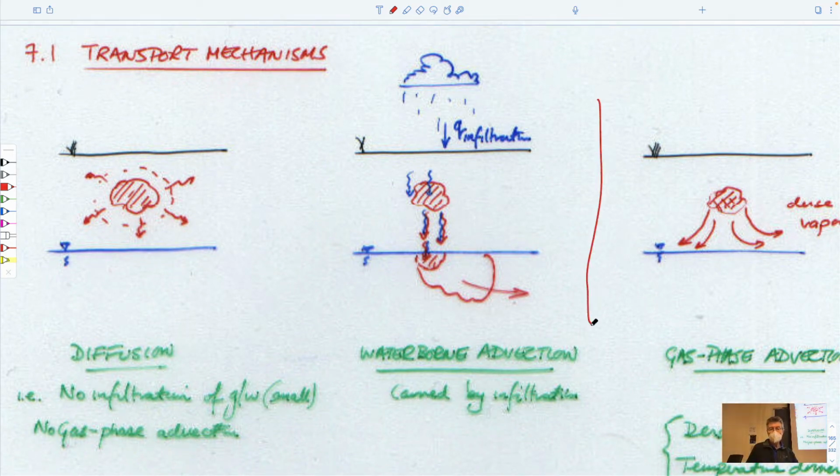They're kind of shown in cartoon form here. This is diffusion, and this is aqueous advection, as we've just described. This is driven by Fick's law, which will drive the transport on concentration gradients. This is a moderately effective way of moving the vapors around, but not as effective as perhaps dissolving them in water and transporting them to the vadose zone, to the groundwater zone. And so that's why this is an important one for us to look at. Dense vapor transport might also be important, but certainly not as important as this.